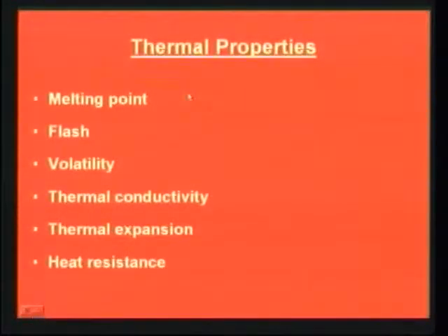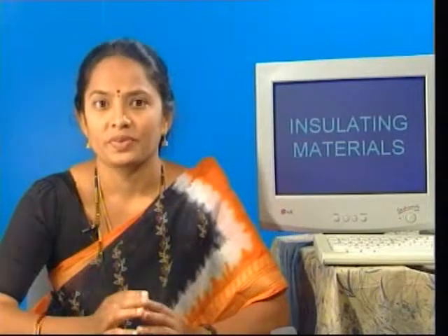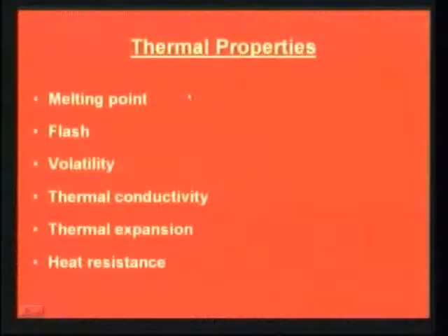The next is thermal expansion. Due to repeated and rapid load cycles to an equipment, corresponding expansion and contraction of the insulator occurs, leading to the possibility of the formation of voids. When two insulating materials combine to form an insulating system, due to two different coefficients of thermal expansion, formation of voids is inevitable. This void formation plays a major role in the breakdown phenomena.